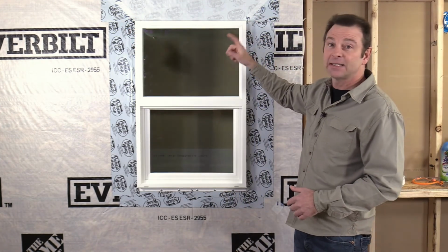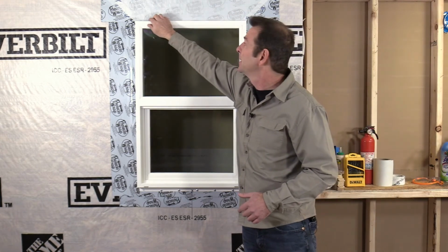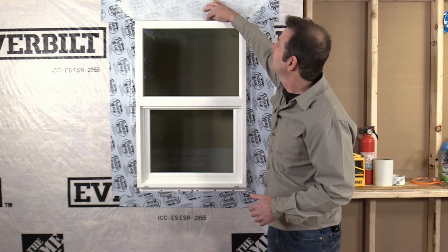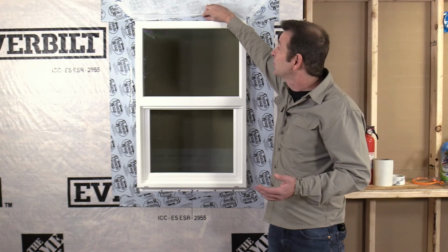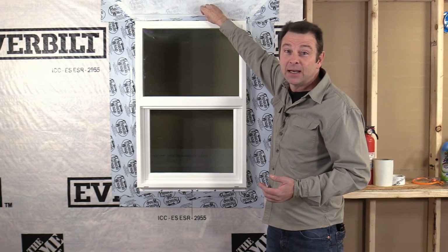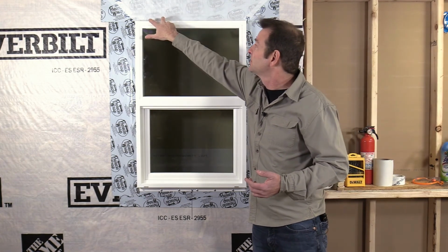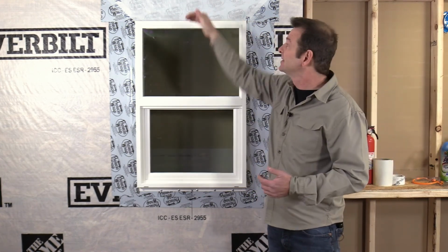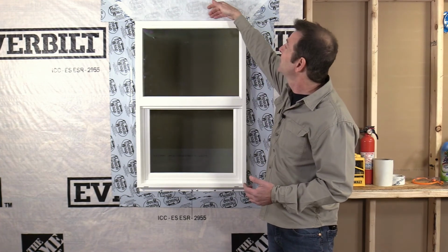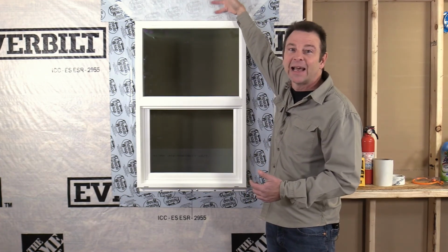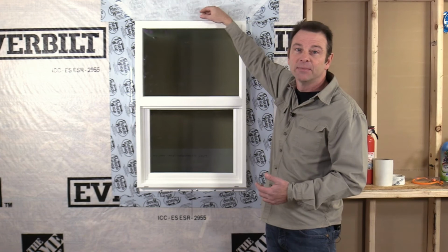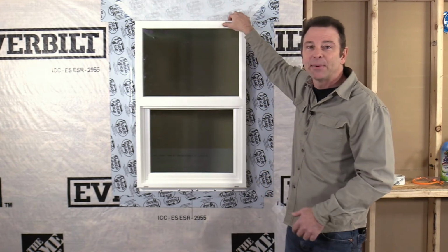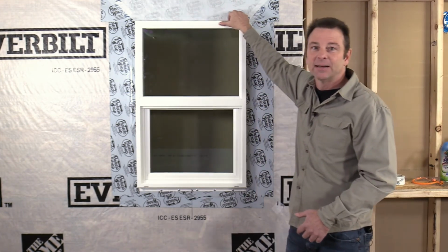What you should not see is a continuous taping of this house wrap here. What you might see is what's called skip taping. They might recommend to have several short pieces of tape to hold this flap down, but keep in mind, just like down here, we want to make sure that that drainage plane allows any water out from this top flap. We don't want to trap any water up here by sealing this up.